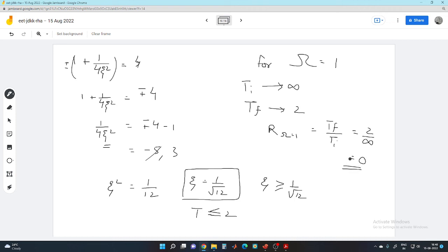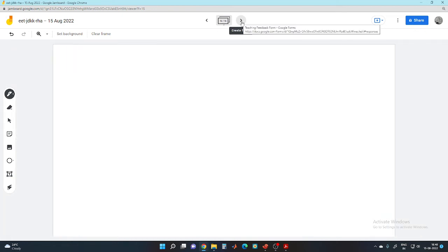So it is an infinite times improvement, or the transmissibility is reduced, with respect to infinite any finite value is 0. So this is good. The resonance failure is avoided.